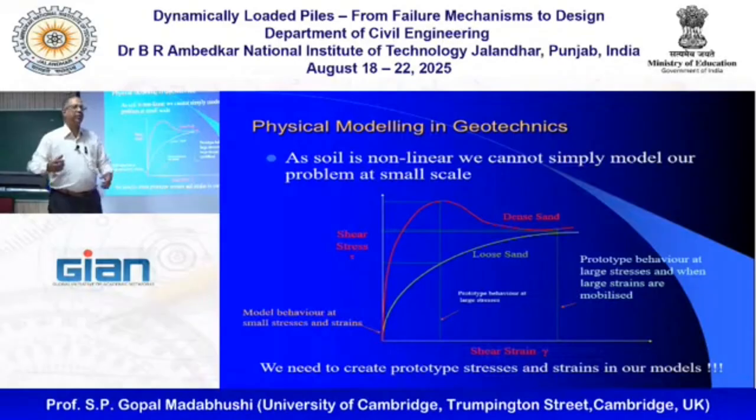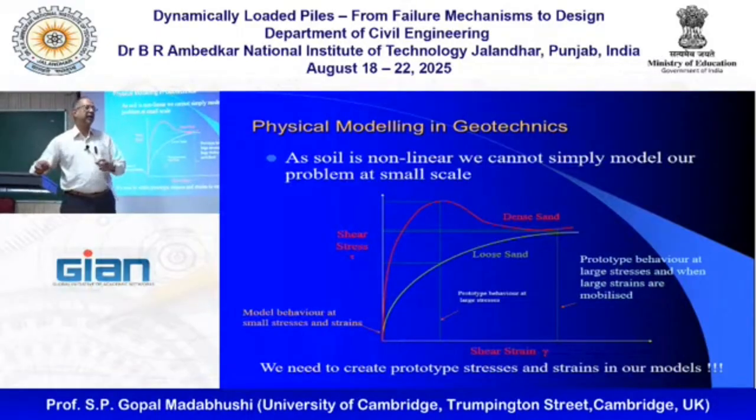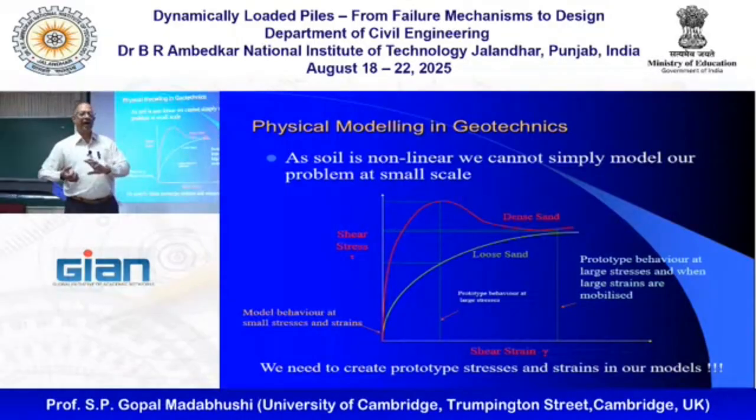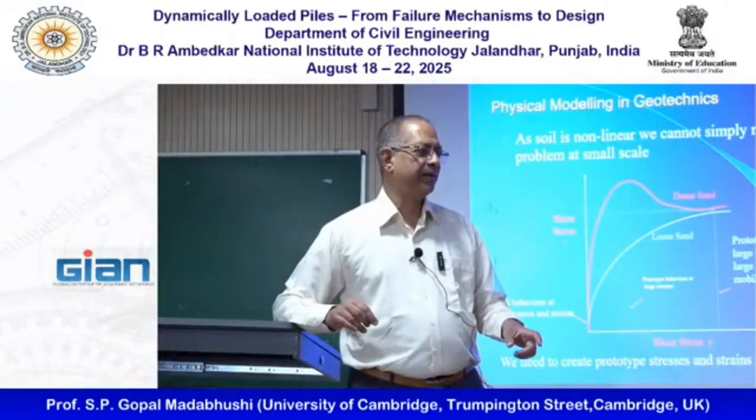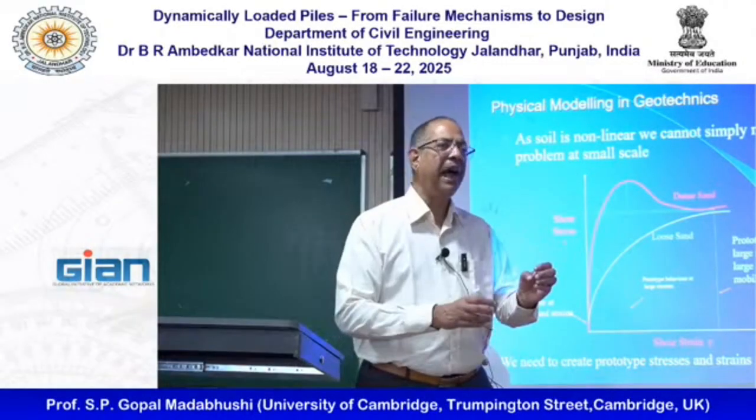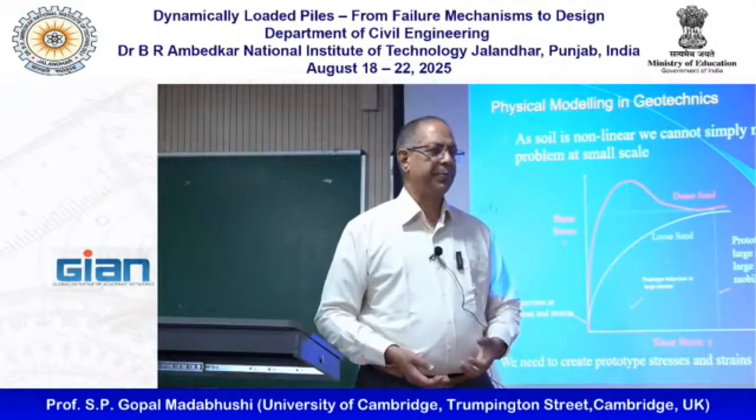In a hydraulics lab, they would have scaled so that all the critical values are the same, normally like the Reynolds number, Rayleigh number. Hydraulics is full of these non-dimensional numbers. So you make sure that the model and the real prototype have the same Reynolds number, typically.